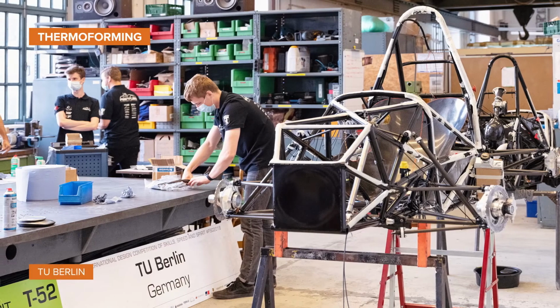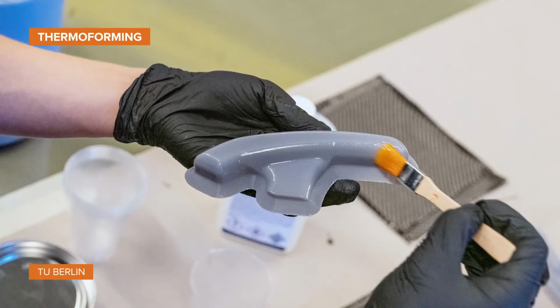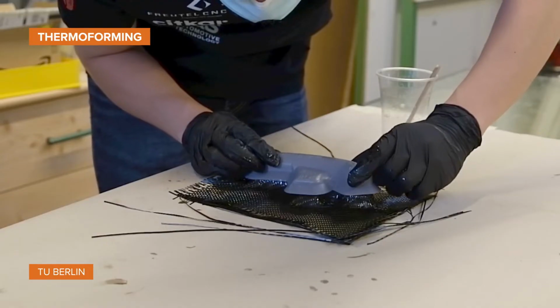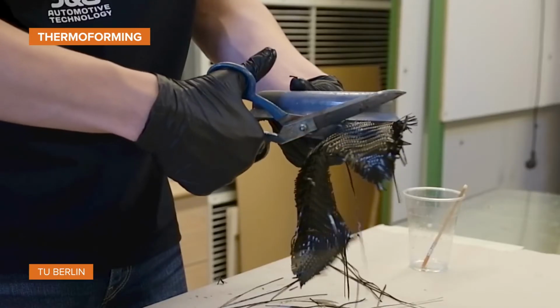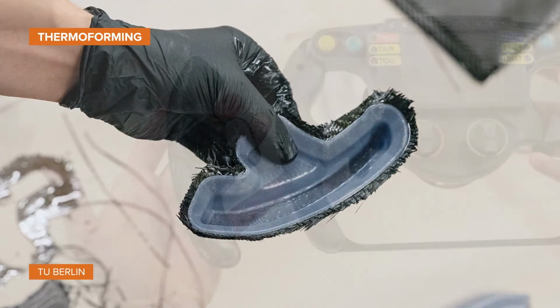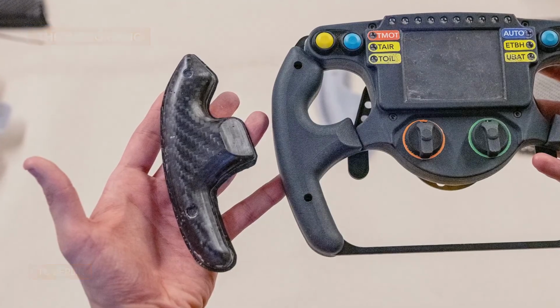The Formula Student team of TU Berlin hand laminates carbon fiber parts on 3D printed molds for racing cars. Printed with Tough 1500 Resin, the mold is not only strong and supportive during the layup, but also sufficiently flexible to separate the part from the mold after curing, unlocking design possibilities.